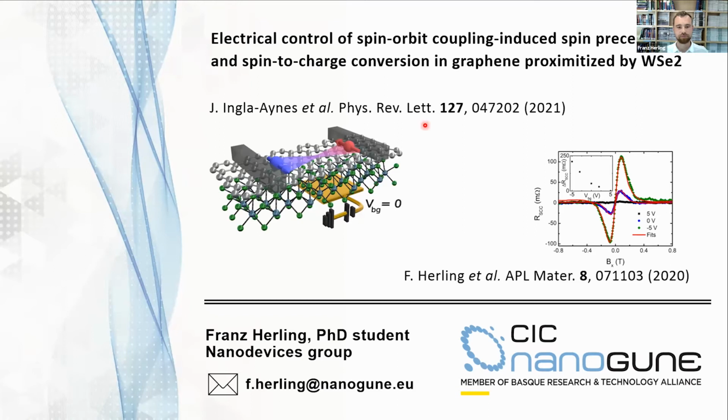I was really interested by that transistor that you showed, the main result of the first section. Did you actually fabricate it? Yeah, so in this sense, this picture is more or less a sketch of the device itself, where we have a graphene channel with a TMD, in this case above, but for the picture we put it below. And these two electrodes are essentially our ferromagnetic electrodes that we use for the device. And we can control one transistor with a backgate voltage and this DC current.